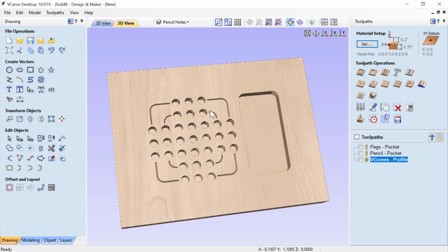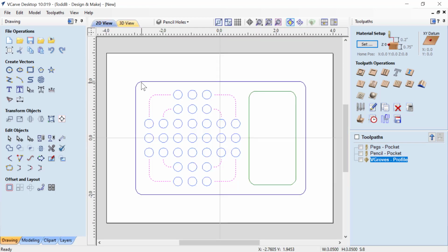The next toolpath, we're gonna pretty this up a little bit by putting a slight chamfer on the outside edge of this pocket here and then around our whole actual board. So let's go to our 2D view. We're gonna select, holding down our shift key, this outside vector. Oh, we also have these selected by mistake, so let's unselect everything just by clicking in the white area. Let's again hold down our shift key, grab those two vectors.